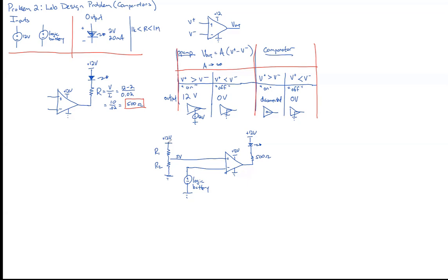Well, at a fraction of an ohm each, you're going to have amps going through this. Just resting, you're going to have amps shooting straight through all the time, and you'll have a huge amount of power lost. In fact, if you have, say, 10 amps flowing through this, 10 amps times 12 volts means you're going to be dissipating 120 watts, about that of a bright, hot light bulb just sitting at rest. In no time, you'd have your car battery discharged.